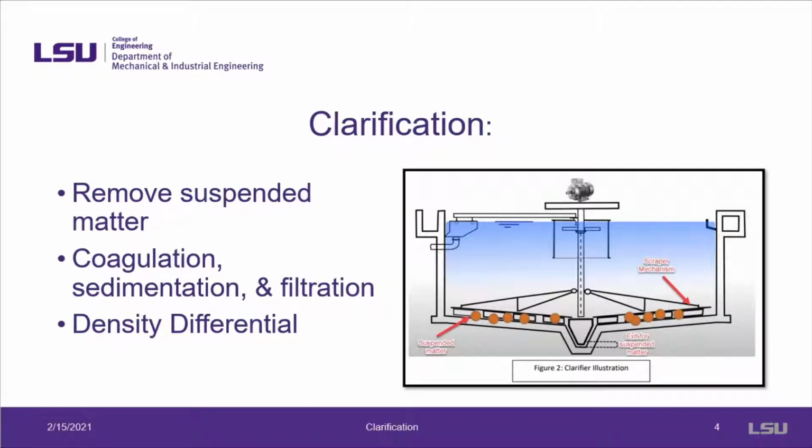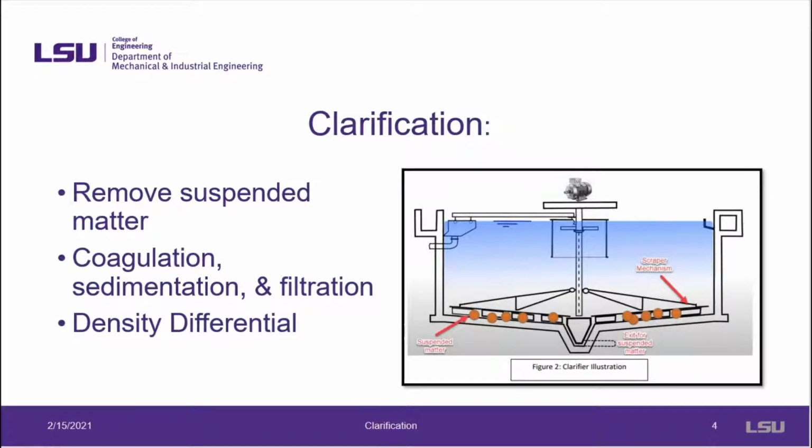The water is then filtered. Cold water filtration systems will use pressure-type sand filters, while hot water filtration systems will use less soluble material such as magnetite for the filtration medium in order to avoid the formation of calcium silicate. Calcium silicate formation may result in a scale buildup inside of the boiler.